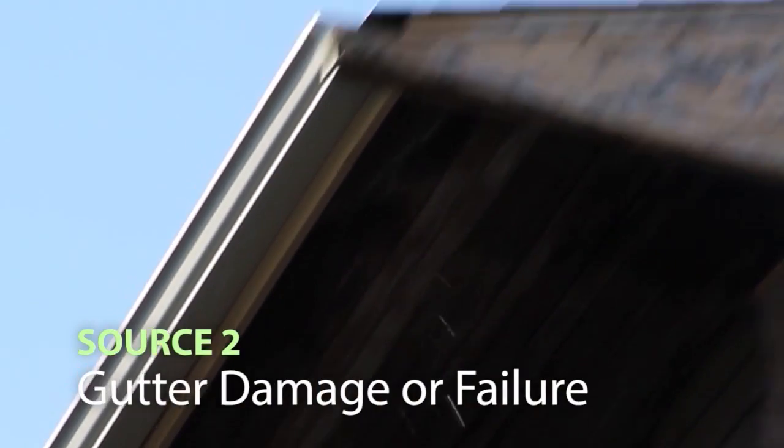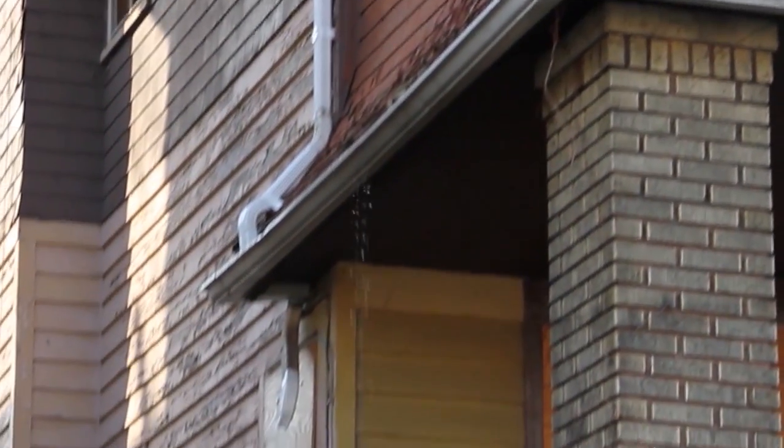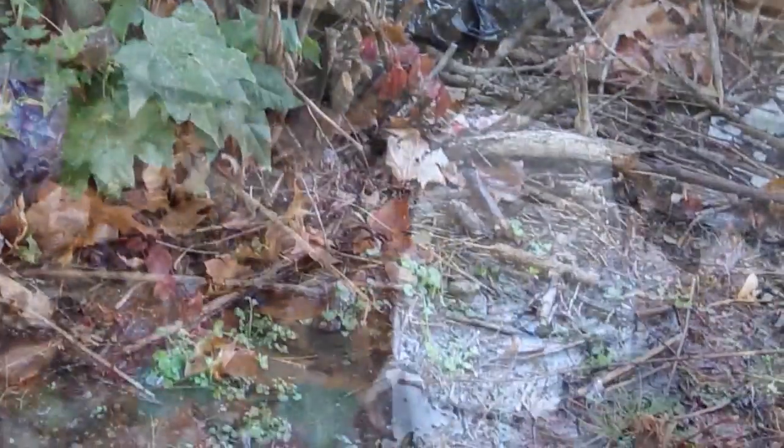Source 2 is gutter damage or failure. Inspect the gutters to ensure that they are not clogged or filled with debris. Also, verify that they are draining away from the property. Check to see if any gutters or downspout sections are damaged or missing, and that all existing pieces are securely intact with the proper hardware.